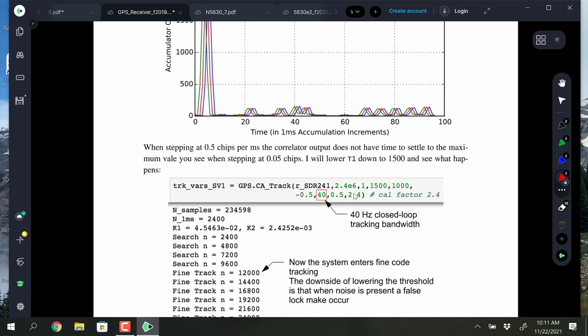Yeah. So when you touch down, I'm just using the example of me traveling, pulling out my GPS receiver, it's starting from a blank slate. It doesn't know at that time of day what satellites it's going to see. Because it just needs to find 4 correlations that are different from one another. Yeah, 4 different satellites. So 4 correlators have to engage on legitimate satellites, and the satellites are always coming and